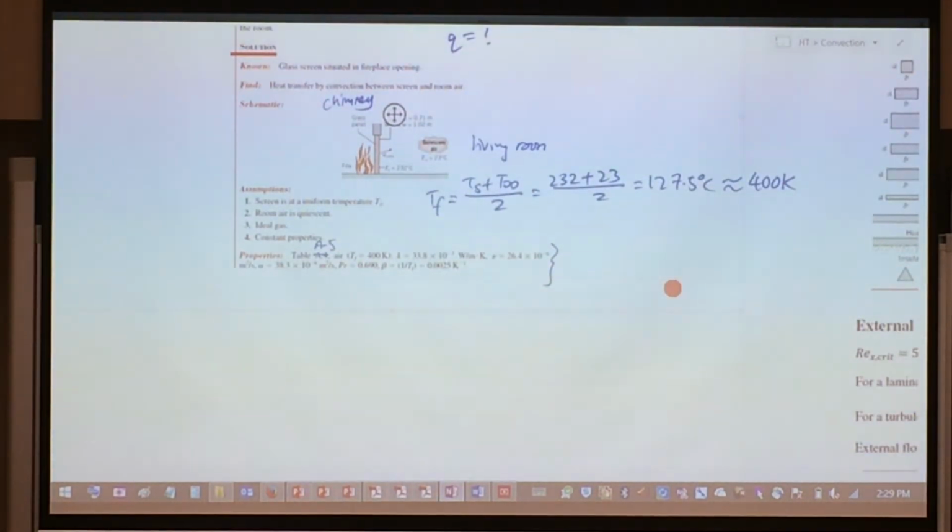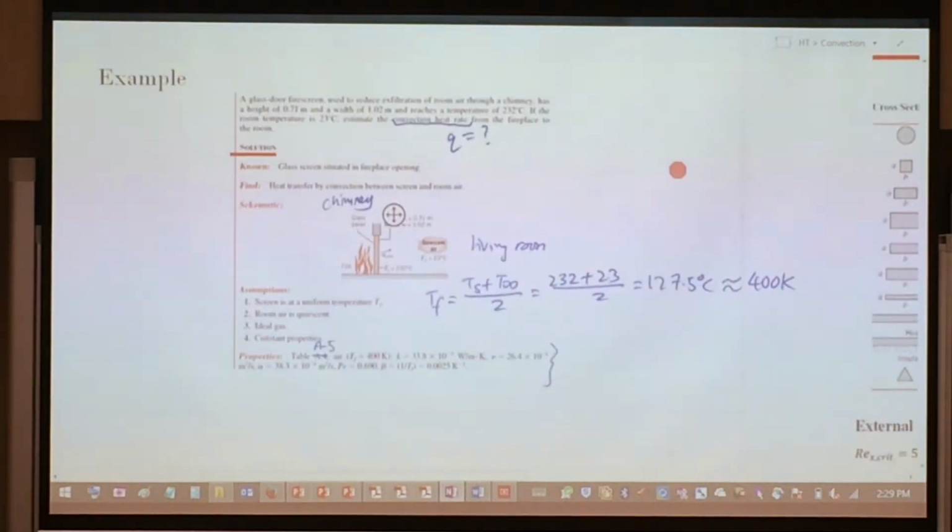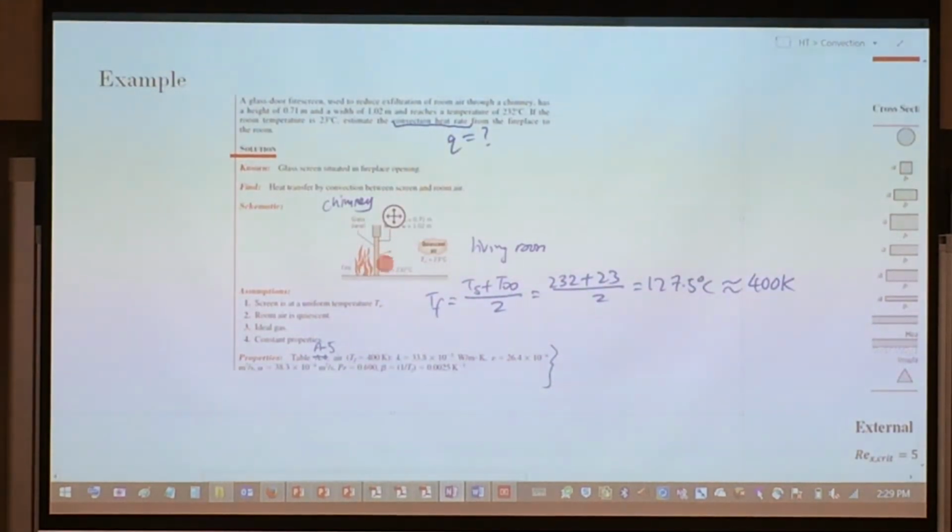So let's go ahead and solve it. We know that for convection, and why I know I'll be looking at convection, that's because this glass is heated up and you have no forced convection over there, so it is actually natural convection that's going on in that way. This is natural convection. And the expression for natural convection will be hA delta T, in this case Ts minus T infinity, because Ts is at a higher temperature than your T infinity.